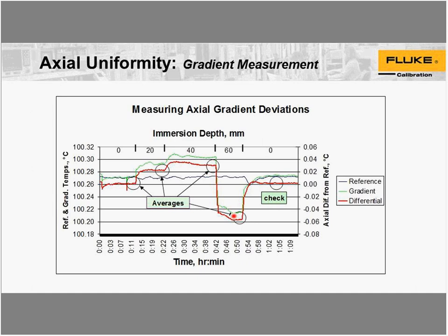And then at 60 millimeters, you'll notice that these temperatures were increasing and finally dropped. That's really typical. What's going on here is when you take a metal block and you heat it with a more constant watt density from top to bottom, it turns out the center is actually the hottest.